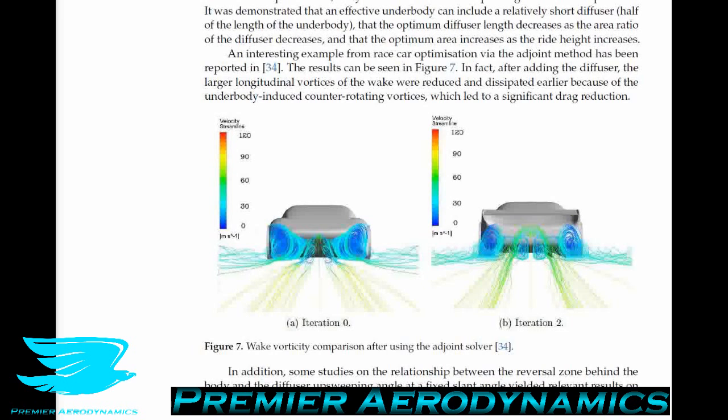Welcome to Aerodynamics class number 143, and in this podcast we'll be talking about underbody diffusers of road cars. We have mentioned in many other podcasts, as well as in our automotive aerodynamics series on YouTube, that car diffusers are very important. And the majority of a car's downforce is usually produced by the diffuser, so like 50% or more. And they do this very efficiently.